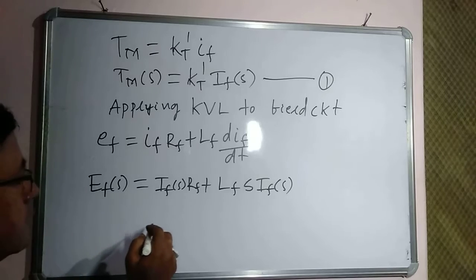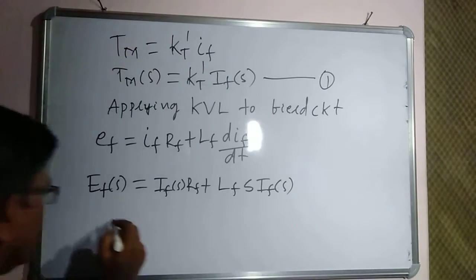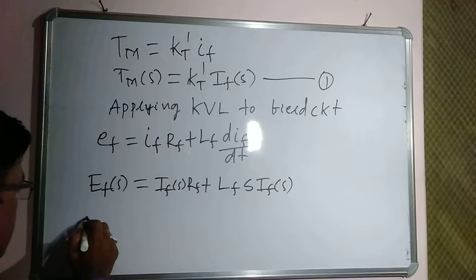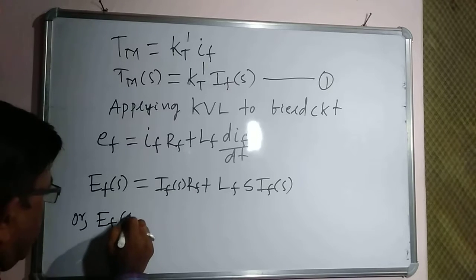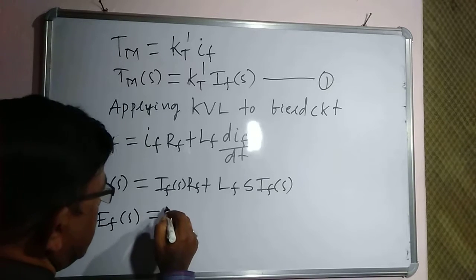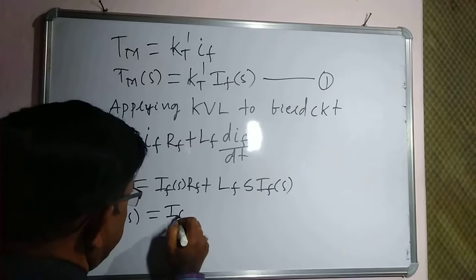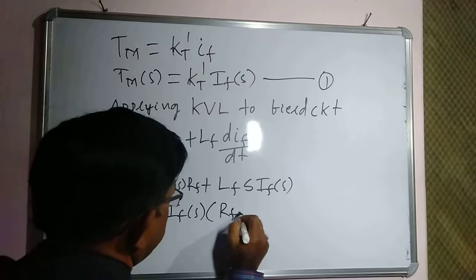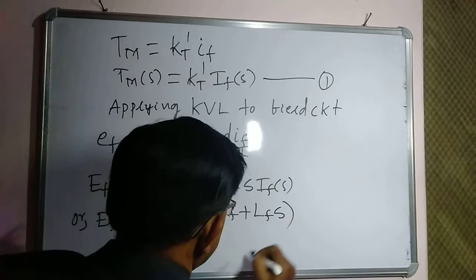So we can simplify this equation again, or Ef of s is equal to, we can take common here, If of s into Rf plus Lf into s.